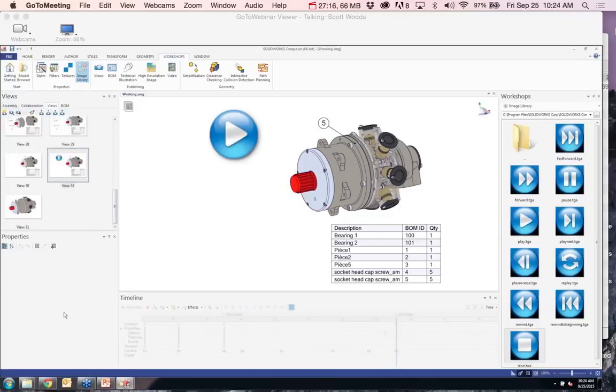Okay, all right. So with that said, we can create all of our steps of the process, and then we can bring those steps into the animation timeline. In the animation timeline, we have full control over setting distances for time or doing our own rotations like this. But the whole purpose of that is not to make an animation. The purpose of this is to make little aids for our assembly instructions.